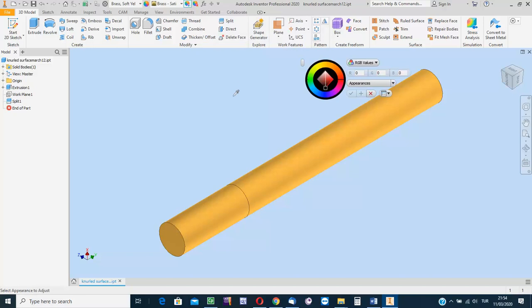Okay, and then in the dialog, find the listing arrow, drop the list, and then scrolling the list, find the Knurl option. Yes, alphabetical order, H, K, and Knurl. Knurl 45 may be selected as the option to have the corresponding surface effect.